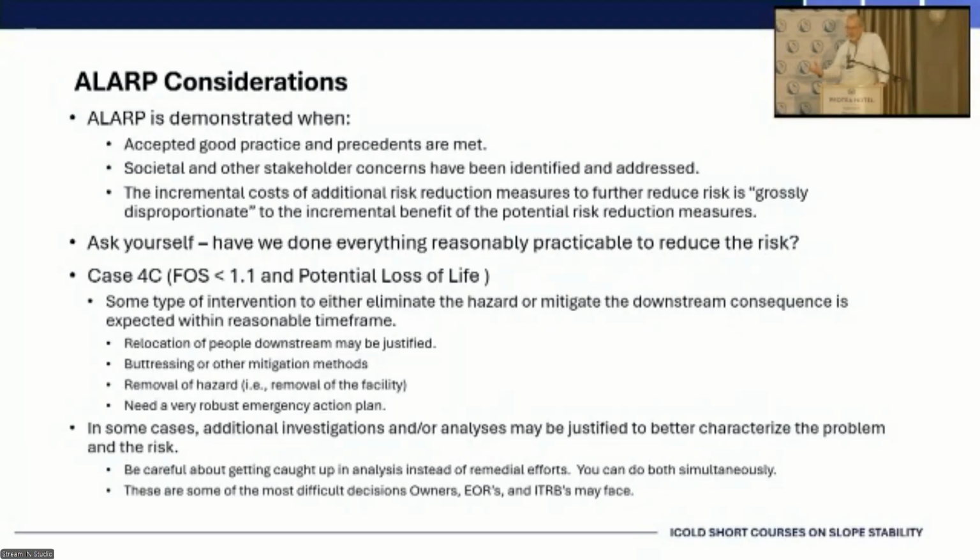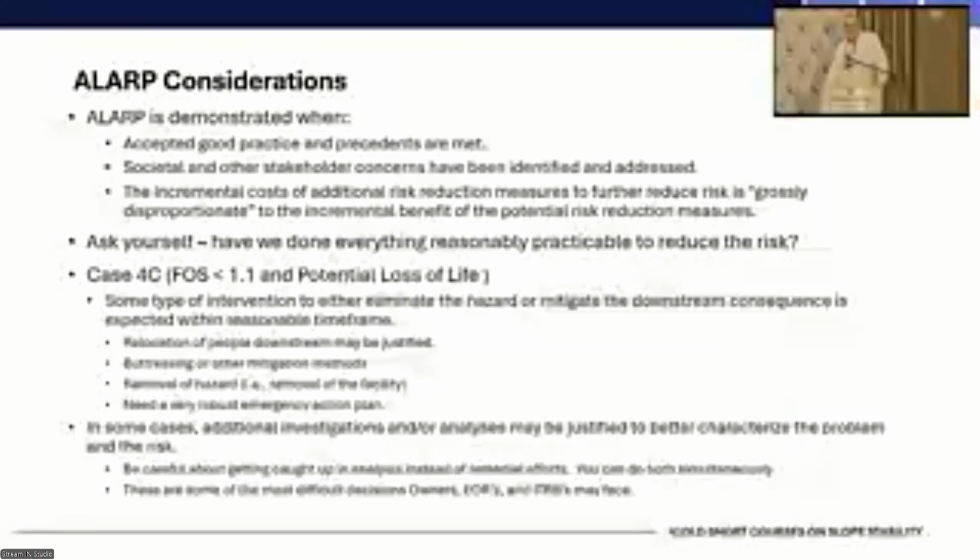All the time, if you're going to be touching the dam, either through buttress construction or any type of modification, you have to make sure that the fix doesn't make the problem worse. So you can't trigger a failure by trying to fix it. So you need to be very careful about that. And certainly need to make sure that your emergency action plan is robust and exercised and ready to go if needed.